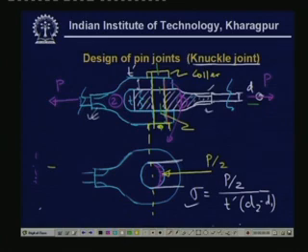There are other things which are not of importance, that is, say the roundness, that is the curvature of it. It is important because you see, if there is no curvature here, then a lot of stress concentration will be developed, but that analysis is normally not done, and this is left to practice. There are handbooks available. We will have to always look to those handbooks, and there are standards there. So, we will have to comply to certain standards.